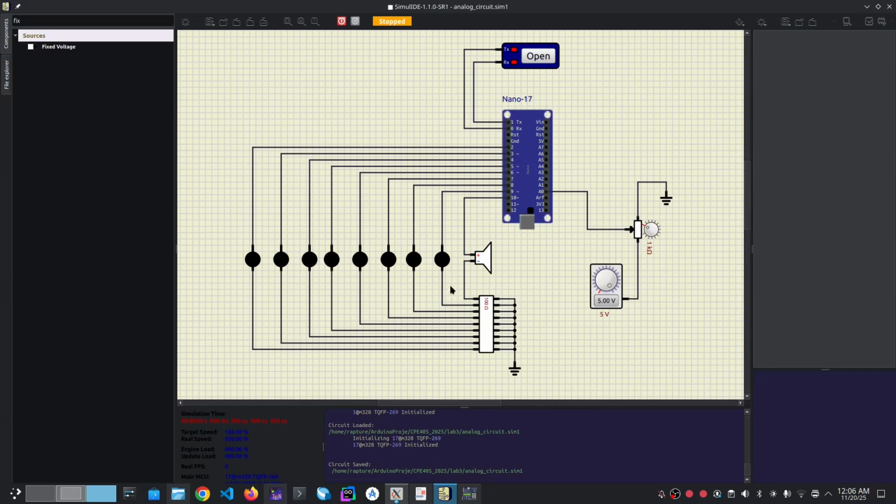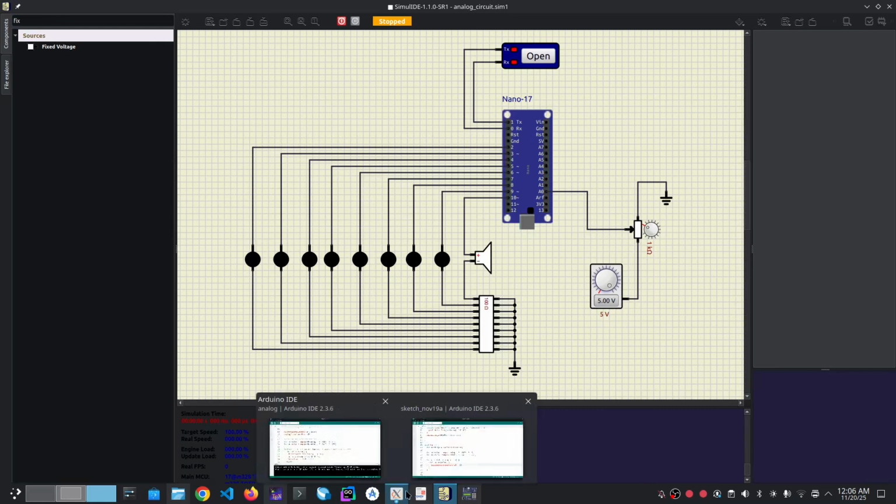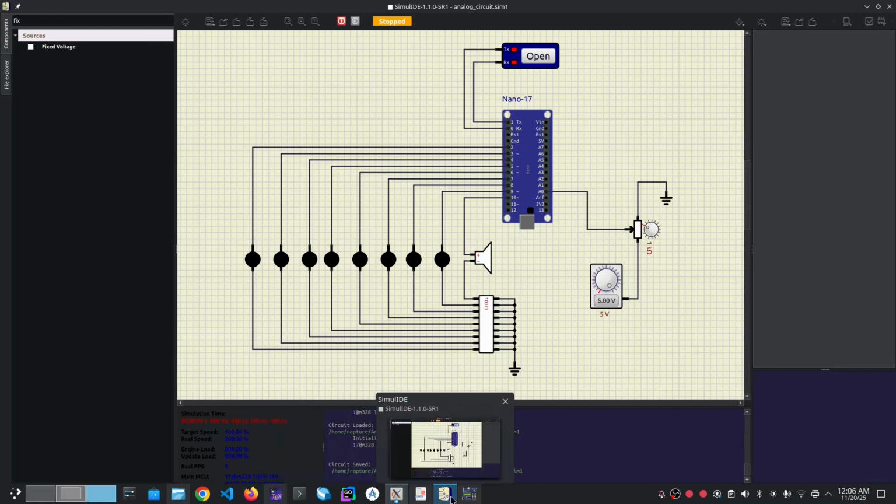Assuming we did it the other way around, where the cathode is connected the other way and the anode is connected to the positive voltage source, that means the low signal will turn on the LED. So you can try that on your own side as a hobby. Also try that on your own for exercise.